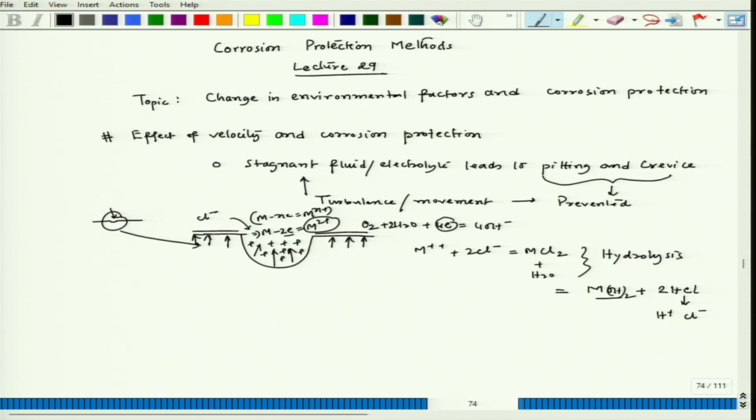Fine. So, now we can see that the hydroxide is forming and settling down, but at the same time you have H+ ion, which increases the acidity of that particular small segment. So, it increases acidity, or pH drops down, and once pH drops down, it actually enhances the attack in that zone. Okay. So, further rapid dissolution of metal would happen in that small narrow pit zone.